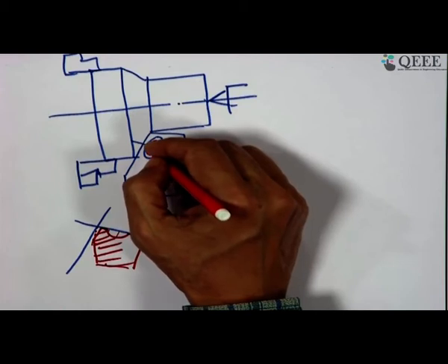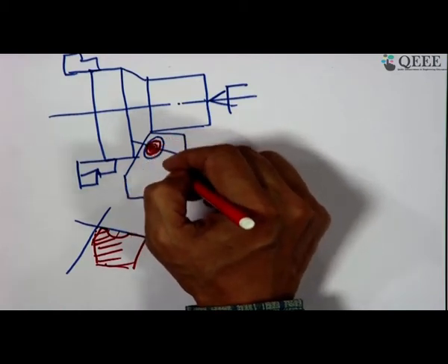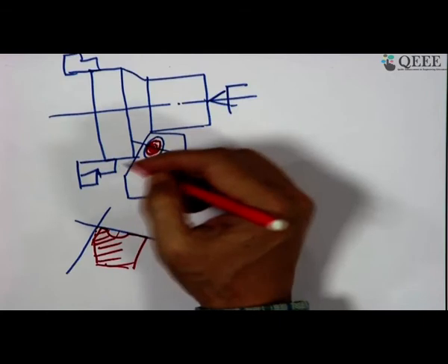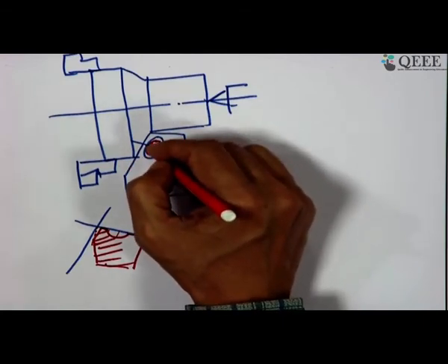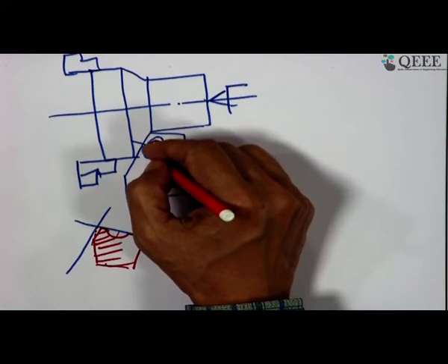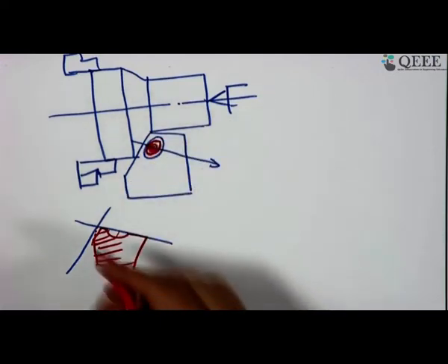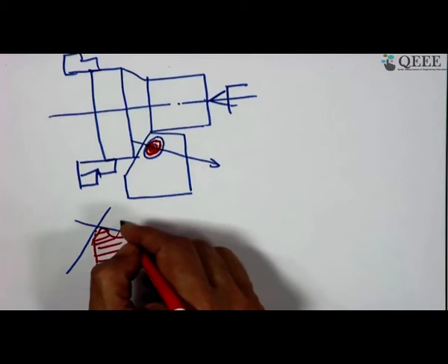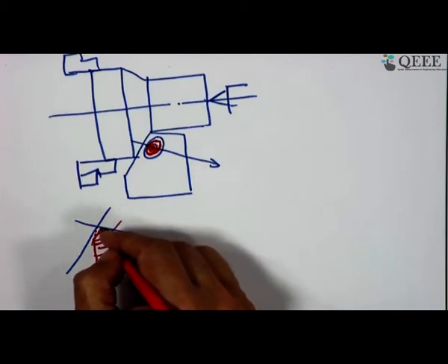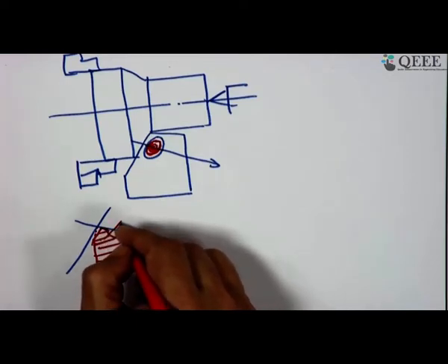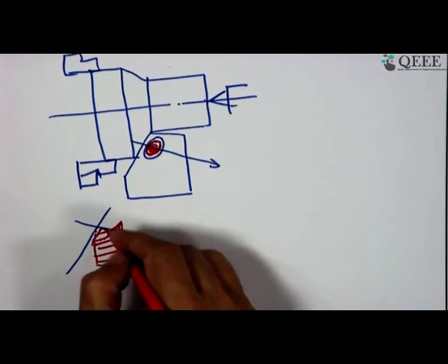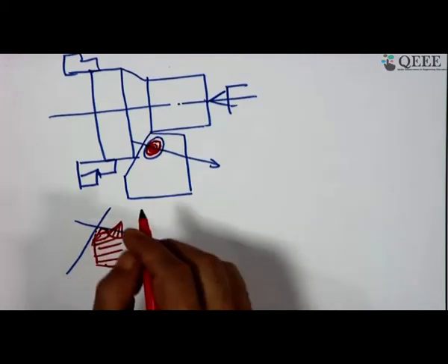Now, this leading edge can advance at a faster rate depending upon the wear resistance of this material, and if it comes very close to this one, that may be very crucial, because the normal force exerted by the chip cannot be borne any more by the small land available. Because of this radial action of this force, there can be a tearing.